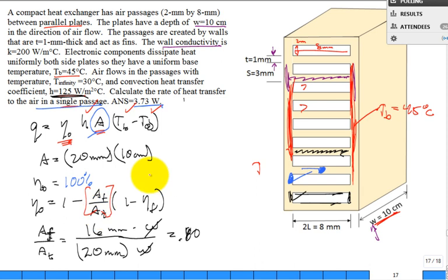Now the hard one. Okay. So we're going to assume it's a constant rectangular cross-sectional fin out to the middle. Out the middle, it's like insulated. And so our formula for that fin efficiency is the hyperbolic tangent of mL divided by mL. Do I need L sub c? No, because it is actually insulated. It's symmetrical. All right, so L is going to be 4 millimeters, 0.004 meters.